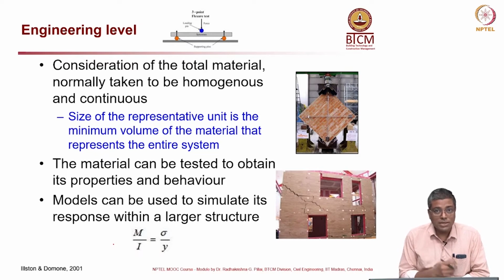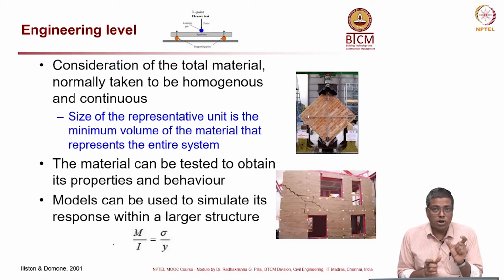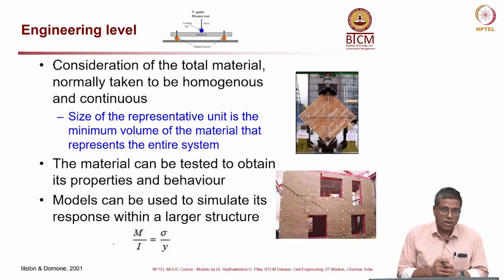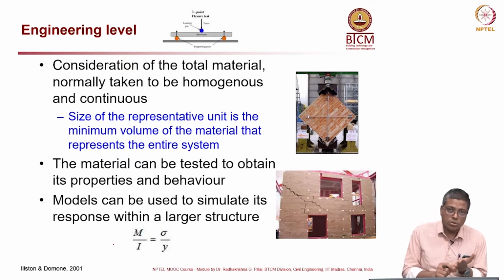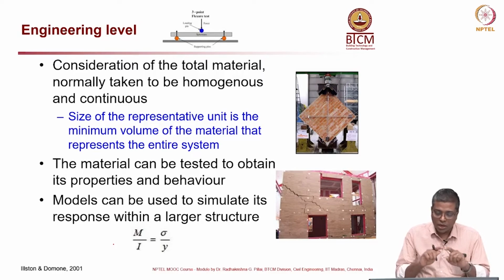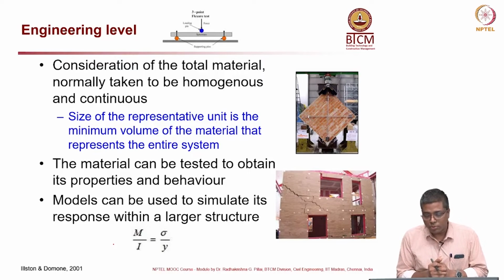When you talk about engineering level, you need to understand what is the size of a representative unit. Here the representative unit is not just one brick piece, but a small area of a brick wall, where the brick which is used and the mortar which is used all play a role in the behavior of that panel which you see on the top right image.